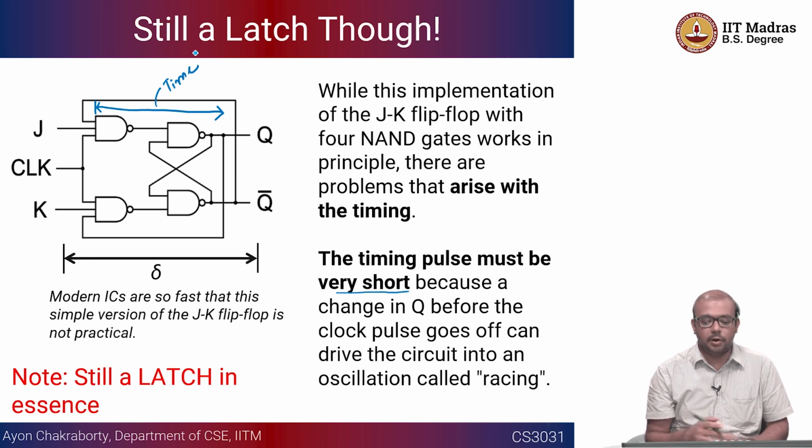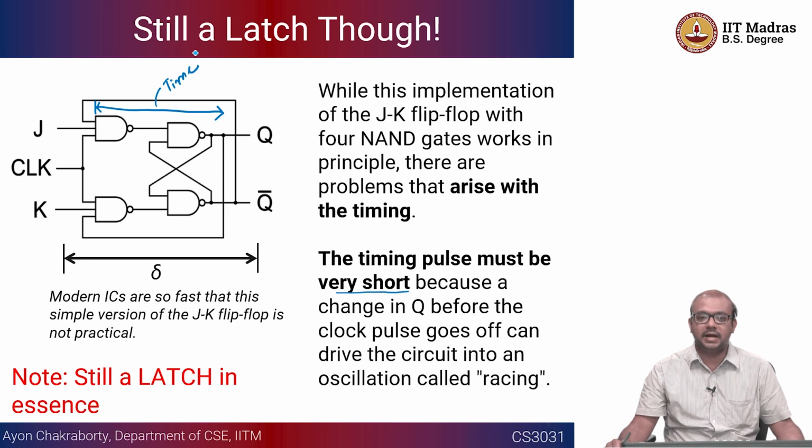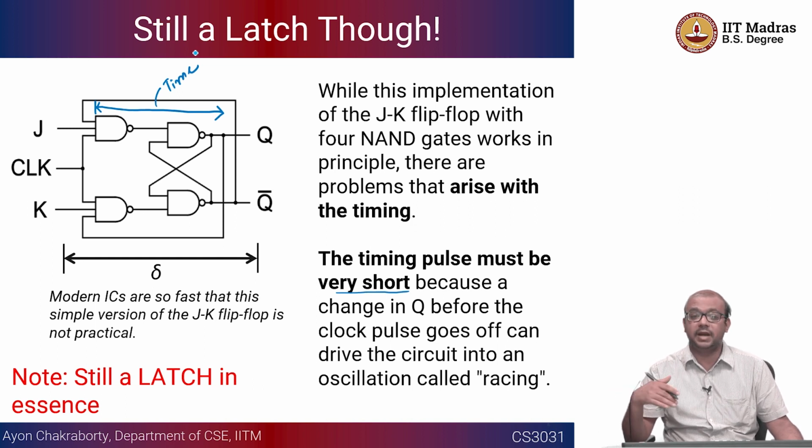Okay, but that is not a reality which is possible, because these gates are very, very fast, right, and this is also not very deterministic, right. So the bit that you get at the end of the day, the computation that you do at the end of the day, has to be deterministic. It cannot depend on the race condition, or on which NAND gate was faster than which NAND gate, right. So we will get answers that cannot be strictly determined.